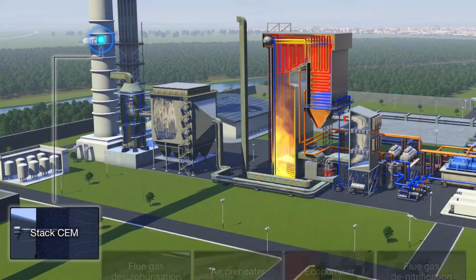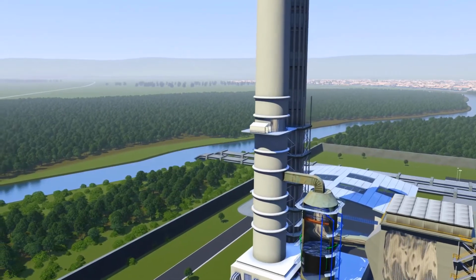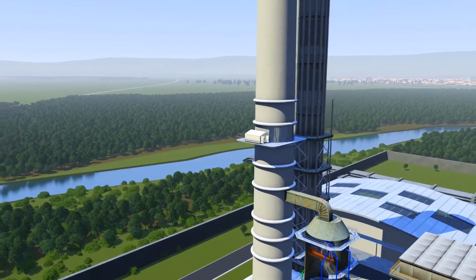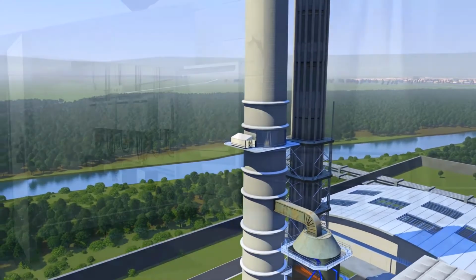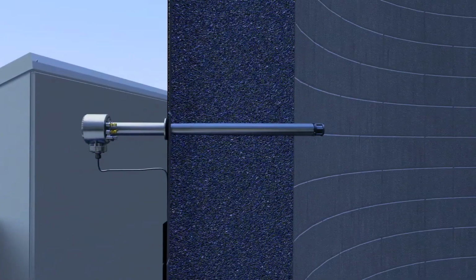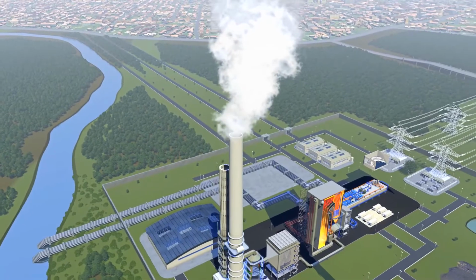Stack CEM. ABB's AZ20 oxygen probes can be used as part of a continuous emissions monitoring or CEM system to ensure that emissions from the flue stack meet legal limits and as a means of checking the efficiency of the combustion process and any associated gas treatment processes.